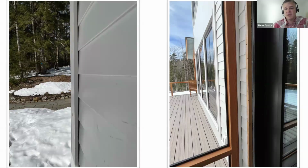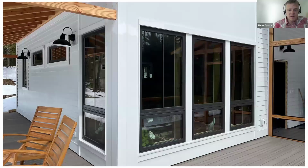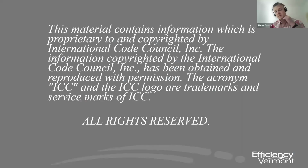You don't have to spend the time of carefully cutting to length each of these pieces of siding because you have the end cuts being protected and hidden by corner boards and by your window casings. And you also don't have to go around the building caulking all of these joints as well too. So just some different ways of considering how to put together your exterior finishes, benefiting from what we know are durable components of the control layers that also make for code compliant assemblies.